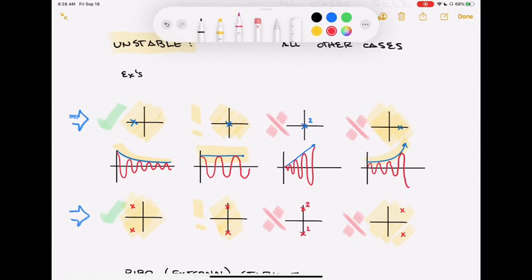By the way, if I had just changed this, let me think about this. Let's go ahead and put it maybe in green. What would happen differently if I put a couple of poles out there? Same real part, like 1. The real part of lambda is still 1. But now I've made the imaginary part larger in magnitude. What does that mean? The further I get away from the real axis, the faster the oscillations. So the oscillatory frequency depends on how far you're traveling vertically. In this particular case, I've moved a good distance from where that red pair of roots were located. So if I looked at that one, it would just go faster, but it would still have that same exponential envelope.